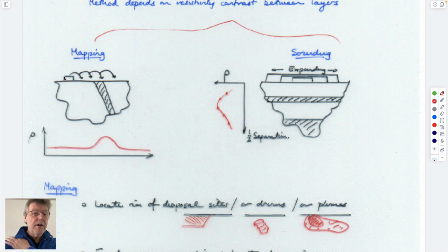So you take this array with these inner measuring components and the outer measuring components, and you measure the behavior maybe at this location here. You take that template and you move it 100 feet over, then 100 feet over, then 100 feet over. So physically you're measuring the electrical resistance below that array at each of these locations.